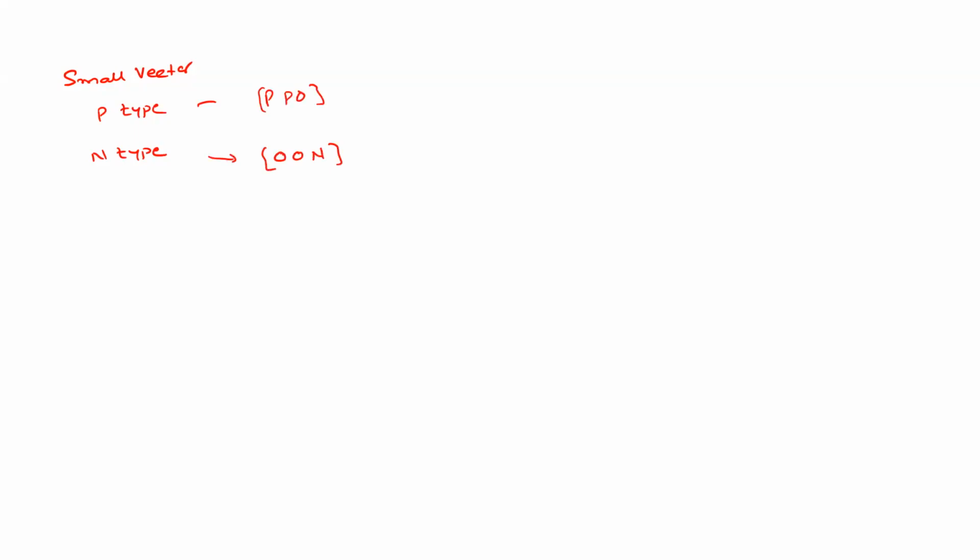So let us see how it will impact the capacitor voltages in the neutral point. That we'll study now. We have the inverter, and it will basically perform two kinds of operation. It may be motoring mode or it may be regeneration mode. In other words, the current is away from the inverter or the current is inside the inverter, so that is a positive current and a negative current.